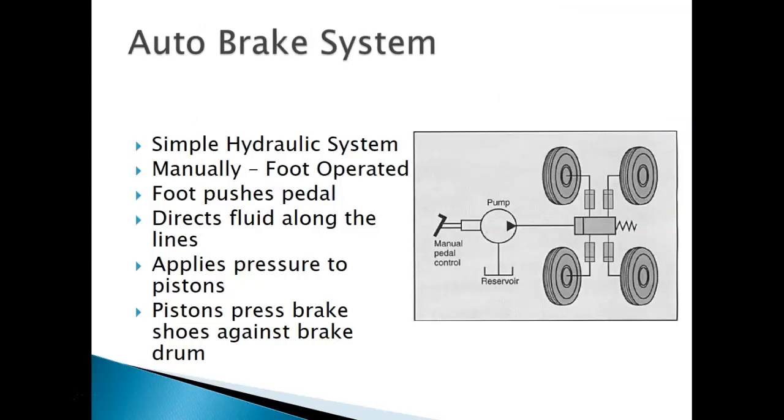The simple hydraulic system, this one's foot operated. It directs fluid along the lines when you press it and applies pressure to the pistons that press against the brake shoes. Press the brake shoes against the brake drum. Same thing with brake pads. I don't know how many of you have really worked on your brake pads and the rotors. But let's say these are the rotors, here are the pads. All the pads are doing is just clamping down. And you can get quite a bit of force with it, right?